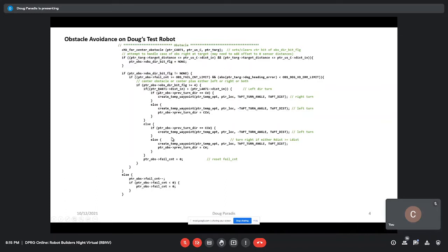So in this case, it looks if the right distance, remember, you saw how my sensors on the forward are tilted in. So the right's really looking left and the left is really looking right. And I decided to keep the convention with the actual physical sensor location and not the direction it was looking at. So in this case, it's saying you want to turn left or counterclockwise.